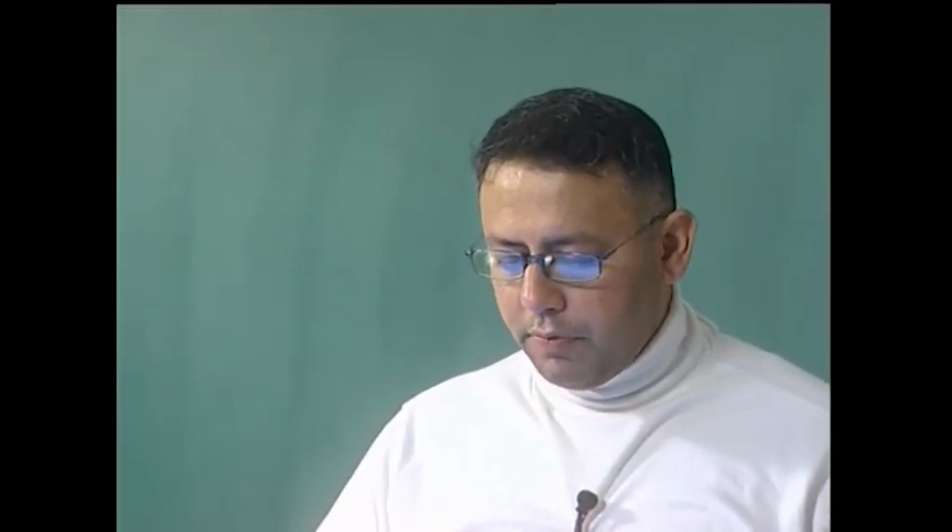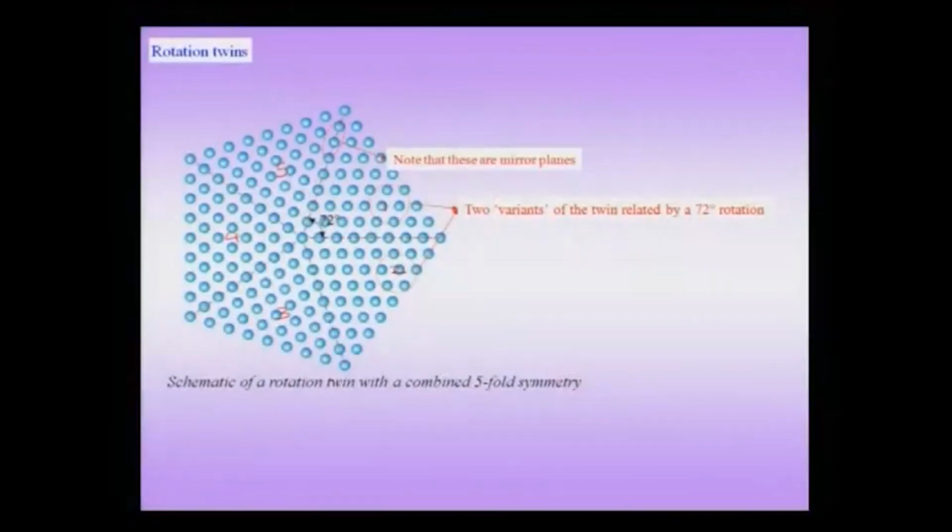The general principle in this area is that the mirror twin, mirror boundary, or the twin boundary, or the symmetry operation I am considering, cannot be the inherent symmetry operation of the crystal. If it were so, then it would be a single crystal and there would not be two variants. Of course, when I am talking about variant 1 and 2, I can also think of this boundary between the two, which I am marking with an arrow, as a sort of mirror twin as well.